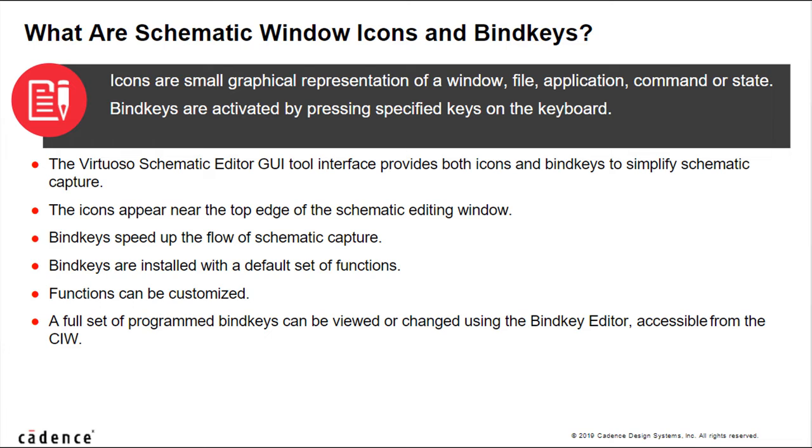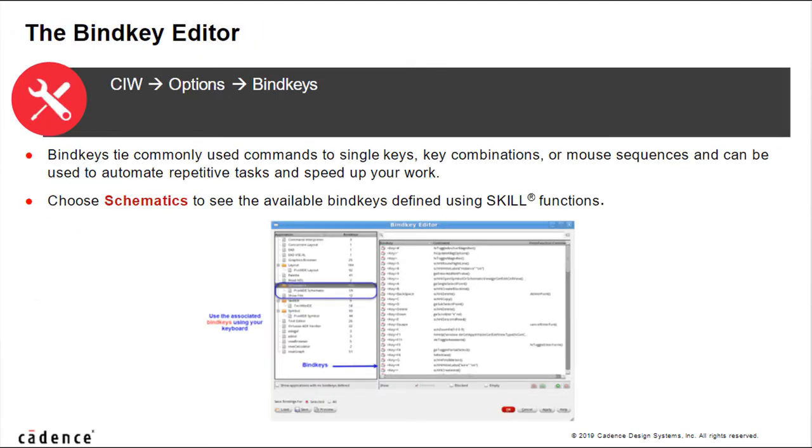A full set of programmed bind keys can be viewed or changed using the Bindkey Editor, which is accessible from the CIW menu. You do not have to remember all the bind keys. You can see them listed for a specific tool in the Bindkey Editor that you can see here on the screen. You can access this from the CIW.